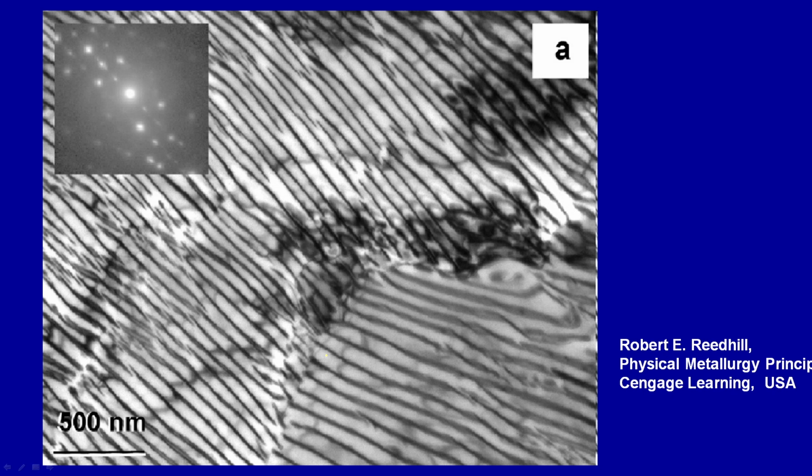So, on a very fine scale, this is how the pearlite will look like, alternating plates or lamellae. You can see the white and black, white and black, white and black, like that. Remember, this is an in situ composite. We talked about composites last time. There is an in situ composite between 2 phases. One is a soft phase which is alpha iron, the other is a hard phase which is carbide Fe3C, and this provides the steel wonderful properties which no material can replace in the world so far.